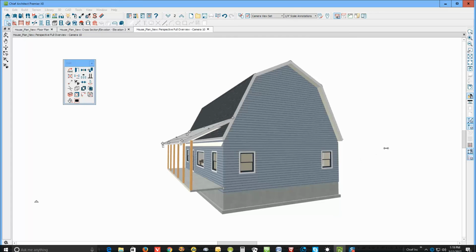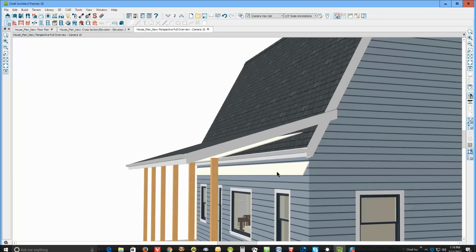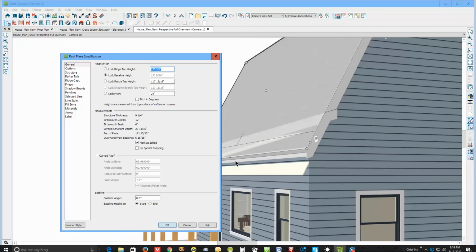You may be up in snow country, and that may be a consideration, but I think that looks a little better. There's nothing wrong with 6, but I think 4 is a little bit better. Now, one thing I noticed, and something a new person probably wouldn't notice, is this white thing sticking down. That's coming from the roof. That's another default setting that you missed.